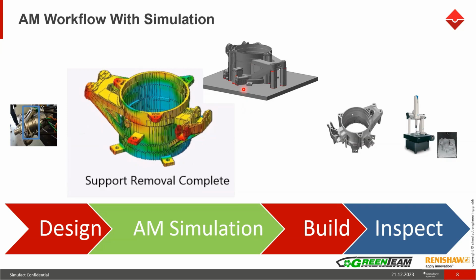If you have those kinds of manufacturing defects, we have to go back to the machine manufacturer. We have to tell them, so they will calibrate the laser accordingly, so that it will fuse the metal properly, and then it will build your part. And one more manufacturing defect that can happen is shrink lines and things like that.